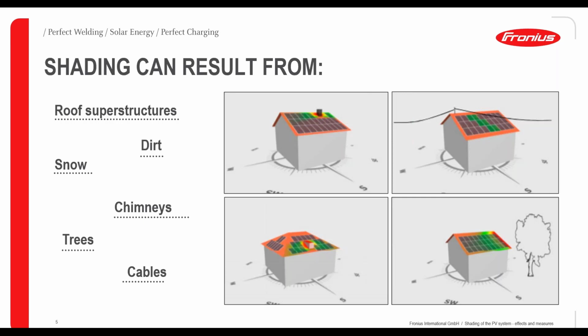Of course, also dirt can be the cause of shading on the PV modules, or snow which is melting and sliding down on the modules, trees from your ground or the neighbor's garden, and also cables, telephone cables, other cables running from your roof to the next, can also lead to a certain amount of shading on the modules.